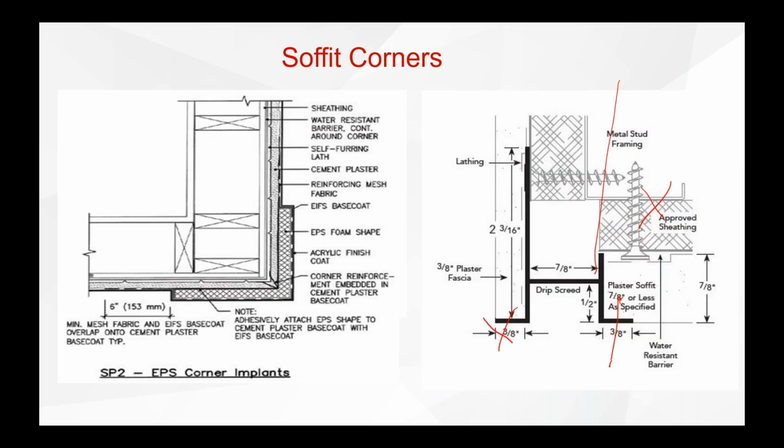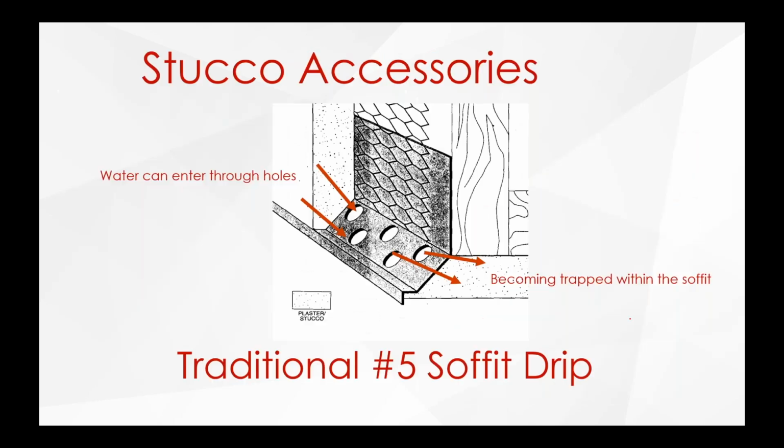Even if you've got aluminum here, this is another good one that will work because there's no capture flange right here. So what's going to happen is that water is just going to drop out here. And again, this is separate from this. So that's key in soffits.